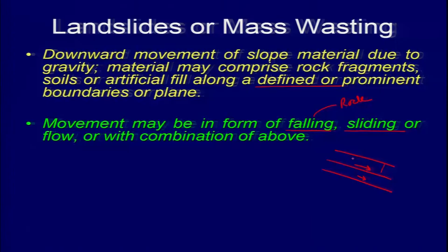Joints will be either vertical or inclined, but that again will be very important because that will affect the shear strength of the material. So either fractures or joints in the succession, or the movement may be in the form of flow, or a combination of all three. If you are having a fall, it is mostly in areas with rock blocks sitting loose.